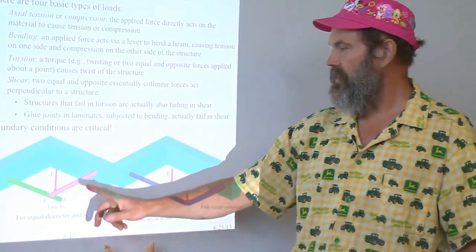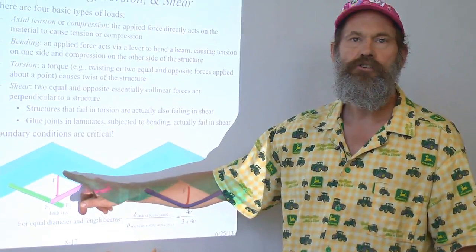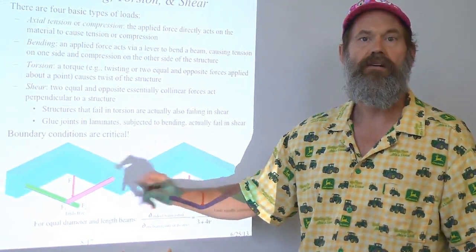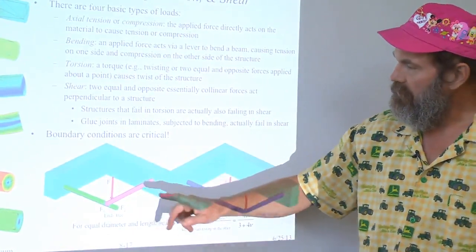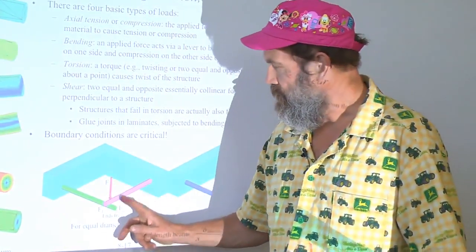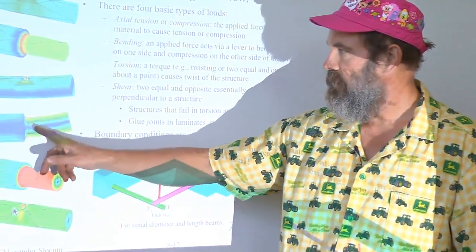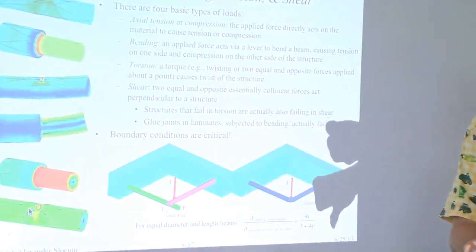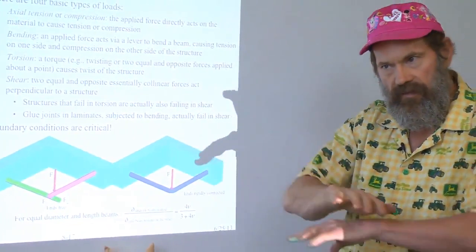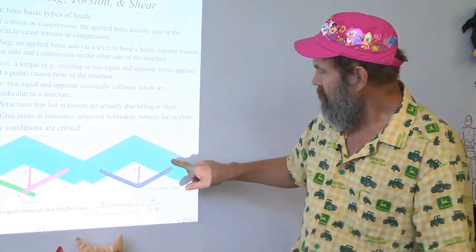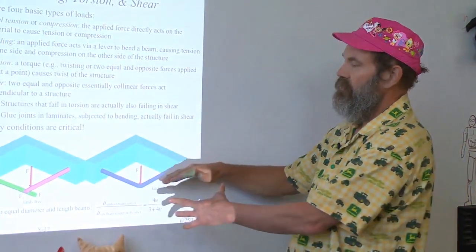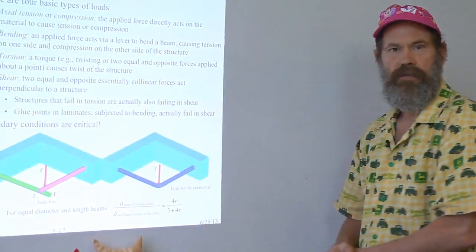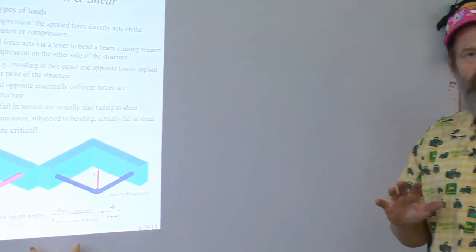The stiffness and strength of joints becomes an issue to be wary of, in particular the strength issue, when you have stress concentrations wherever there is a physical joint between things and you have a discontinuity. When I form something, I can often put a nice, big, gentle curve in it, which can help to reduce stress concentrations.